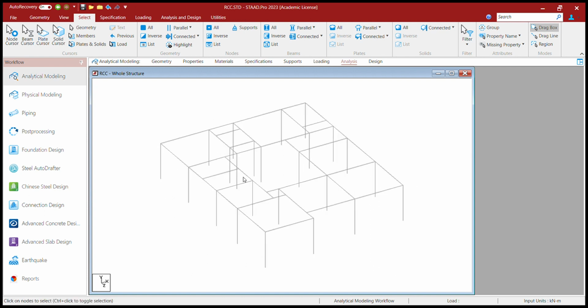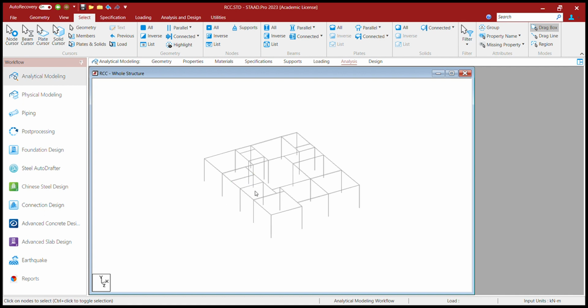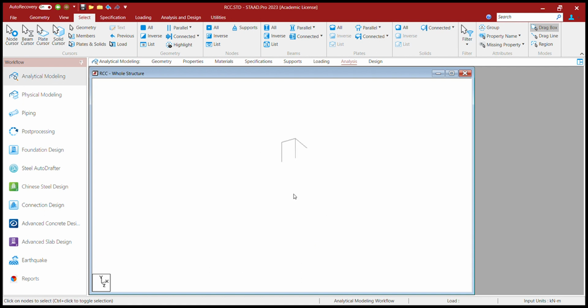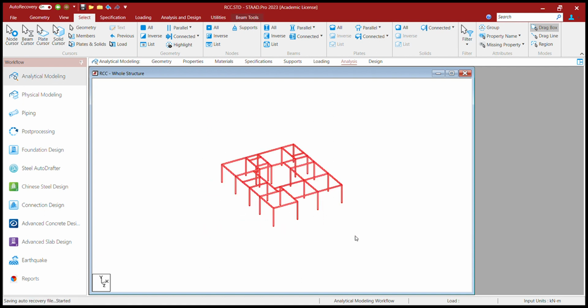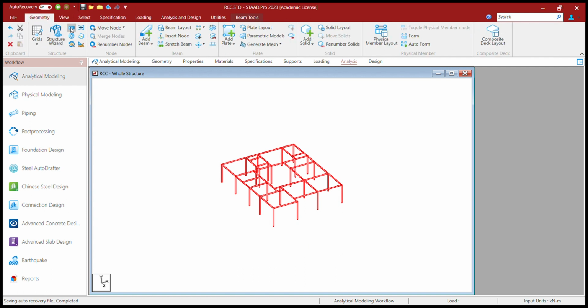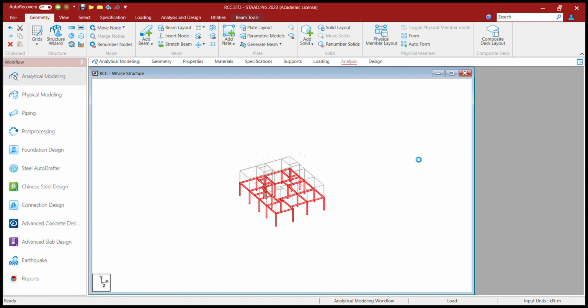Okay. So now this bottom story is completed, right? Bottom story is completed. Now we'll select the total structure. We'll use the translation repeat in y direction with a number of steps. Suppose we want a G plus 7 with a default spacing of 3 meter, and let's click OK.